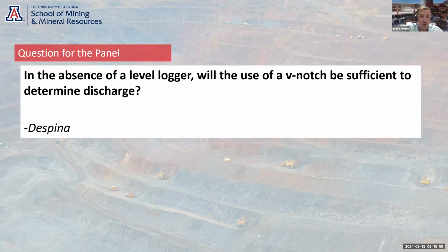Just be careful when you're using percussion methods that aren't reverse circulation airlift. Bear in mind that the compressed air being pumped down the hole can affect the reading on the VWP or the water level in the monitoring hole, open standpipe or pilot hole nearby. But yes, we commonly use this. It's the cheapest way to get a blow yield. But you need to use that information carefully, and ideally you only rely on it once you've built up a register of a number of boreholes, more than 10, closer to the order of 50 or so. Then you can use it reliably. But for greenfields, ideally you want to do reverse circulation airlift or a pump test, aquifer test.